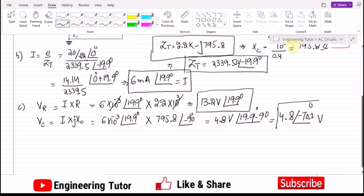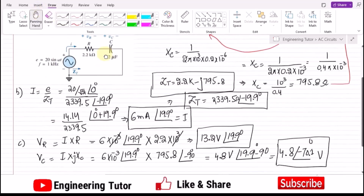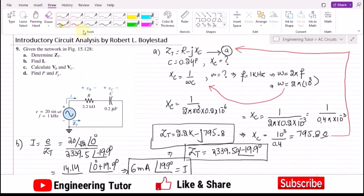So that is also in volts, and this is the voltage across the capacitor here. Okay, you can also verify whether all the voltages available in my circuit obey the KVL by using the formula E equal to VR plus VC, and you will see that the phasor sum of VR and VC will eventually give you the value of E, and that value will be 20 divided by square root of 2. Okay, so you can very easily find them out by using the procedure which I have previously shown you. Okay, that's it for this part of the question.